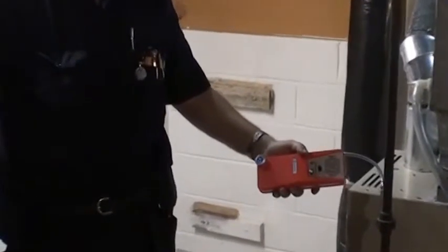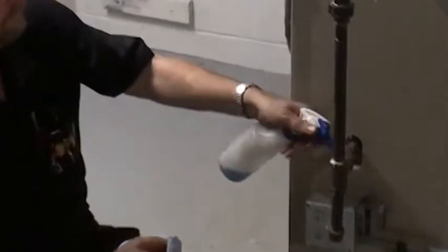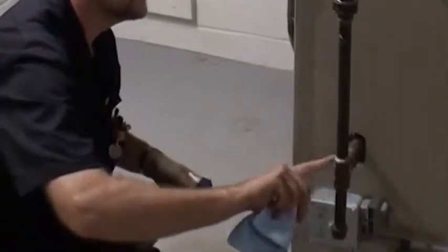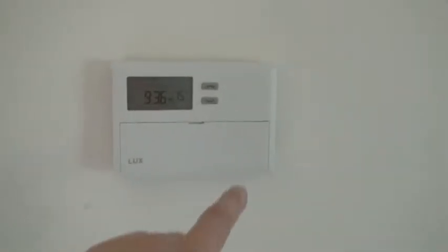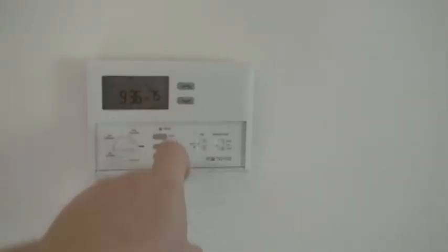Ensure that gas lines have no leaks and there are sufficient gas drip legs. If a gas leak is found, repair as needed. Test thermostat amperage if the thermostat has an adjustable anticipator. Measure amperage of the gas valve and any other low voltage equipment on the control circuit and set the thermostat heat anticipator to match. Test digital and setback thermostats for optimal performance.